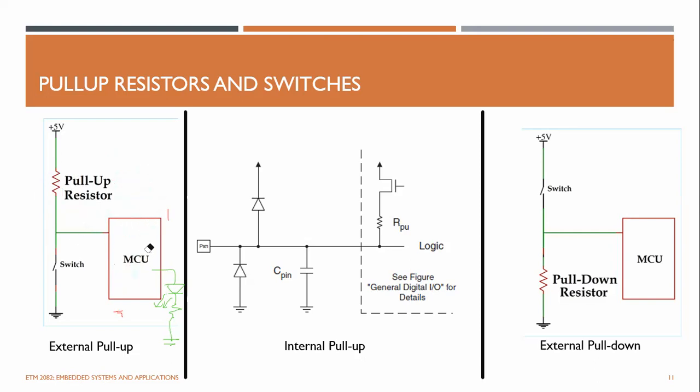Now, if someone presses the switch, the pin voltage should change. Initially, it is at 5 volt. Now, assume someone comes and presses this switch. He just pressed this switch, short circuiting, and we know there's a high impedance resistance here, which is infinite. So what is happening is you short circuit with a wire, and there's another infinite resistor.